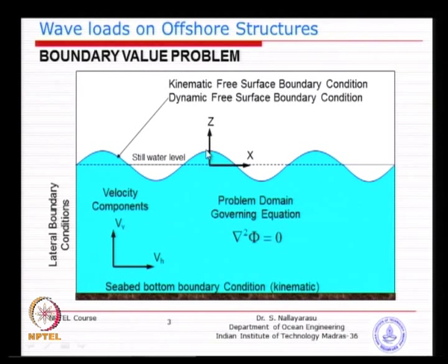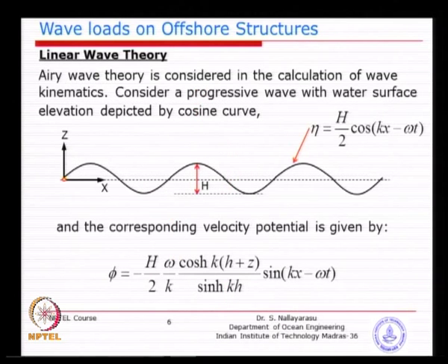Basically the final equations will be the same, only the substitution has to be done accordingly. In this case for the seabed location we will put z equal to minus water depth, whereas if you have the coordinate system starting at the mud line, then z equal to 0 will represent the mud line. So, it is just a transformation.